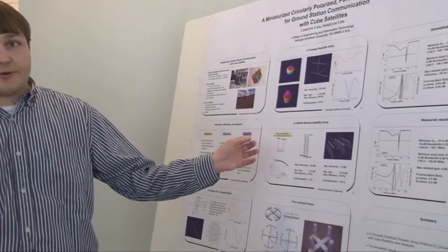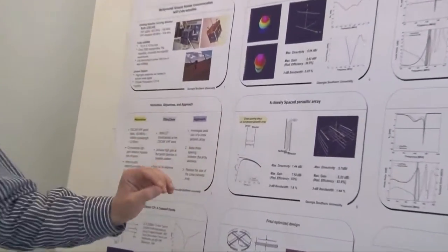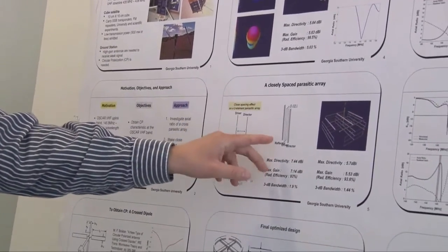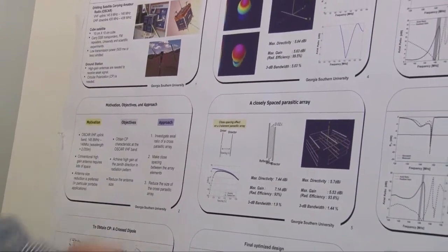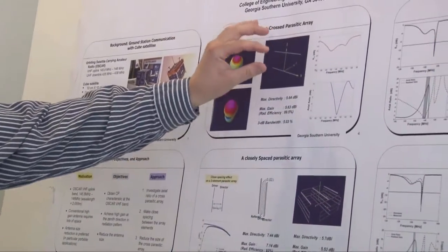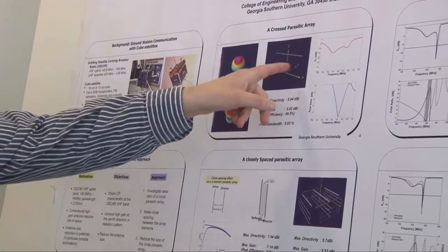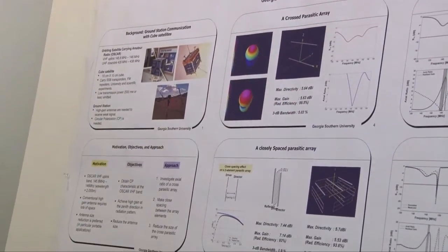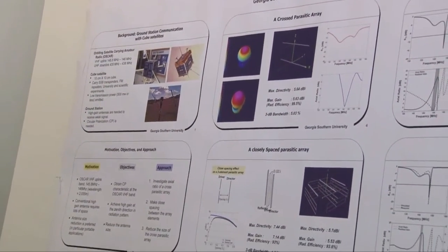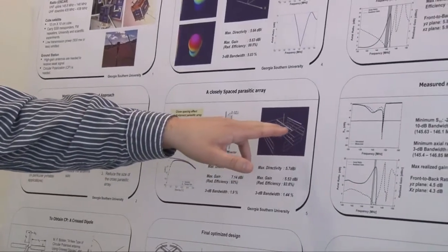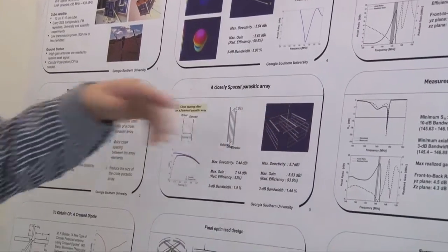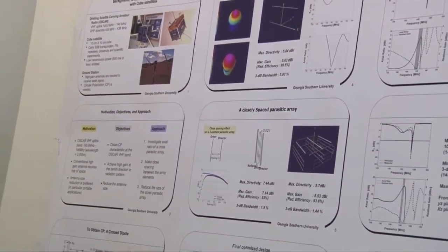To compensate for this drop in radiation resistance, the geometry can be modified with a triple folded design that boosts the radiation resistance back to 50 ohms. That enables the close spacing. We still need to miniaturize the actual elements themselves. To do that, you could use a geometry size reduction technique known as top loading, which can be seen here. You basically add these bars to reduce the overall length. That adds capacitance to the antenna and allows it to be smaller than its electrical size would otherwise require.